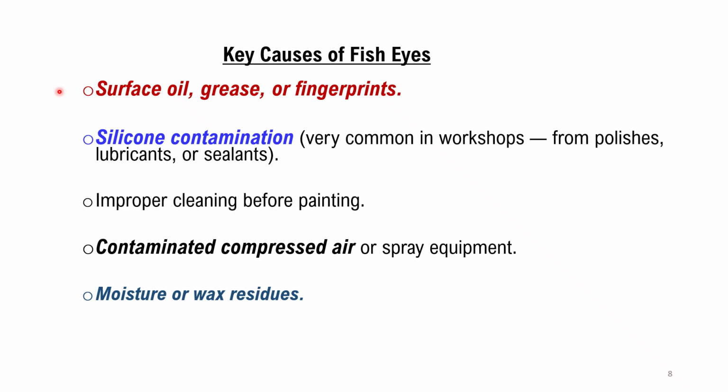The second cause, silicone contamination, very common in workshops from polishes, lubricants or sealants. The third cause, improper cleaning before painting. The fourth cause, contaminated compressed air or spray equipment. Fifth one, moisture or wax residues.